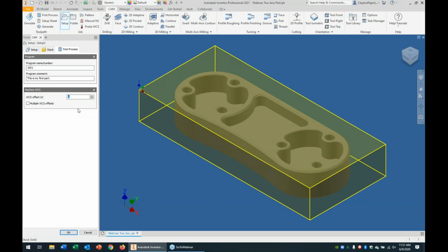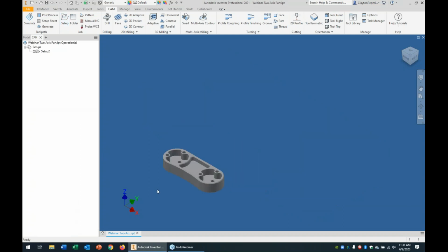We used to have a Fanuc-based machine where it was G54, G55, G56. We also had a tree machine with a Dynapath control on it, and it was using E01, E02, E03, and E04 as fixture offsets. So even though the machines are different, in here, all you have to do is just say it's work offset number 1, 2, 3, or 4. And that also leaves you unlimited. You can have work offset 999. So once you have your setup done, then you're off and ready to machine.